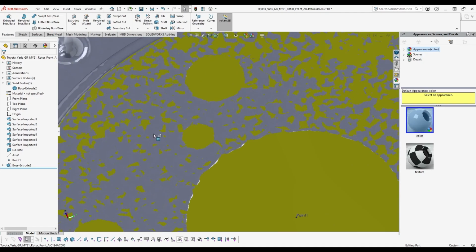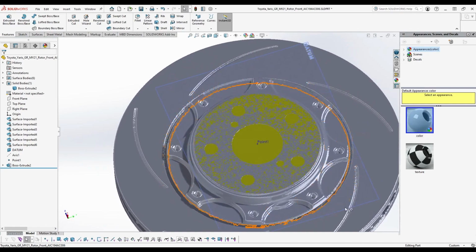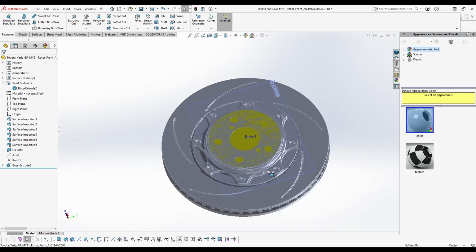And you know, when you get scan data like this that's half patchy, that's very, very close to a fit. So I hope that's been insightful. You can use STLs in SolidWorks. There's plenty of other things that you can do. There's all sorts of science, but in reality, their functionality is most useful in a graphical representation, and the fact that they are accurate. So you can hang your hat on the accuracy being 0.04 of a millimeter effectively for each point cloud. But do always check it. Make sure everything looks like it fits okay.